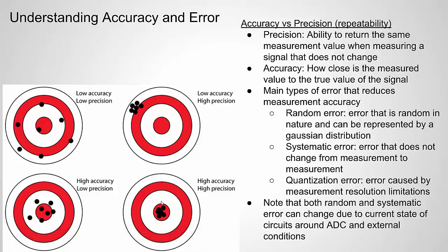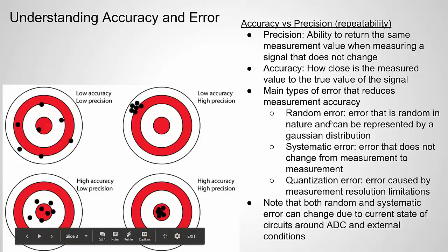I'm not going to talk much more about precision after this, but what's important about precision and accuracy is they can tell us the types of error we're seeing in our measurement, right? And it's important to understand the type of error you're seeing because then you can take actions to correct it. Some of those actions we'll talk about in this series, or you might know what the source of the error is. So we can have random error caused by random noise.